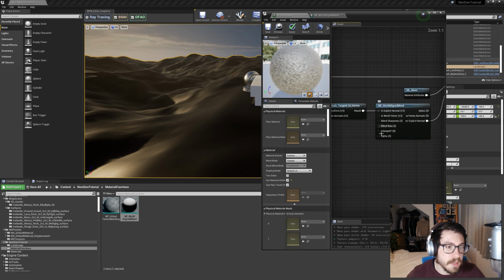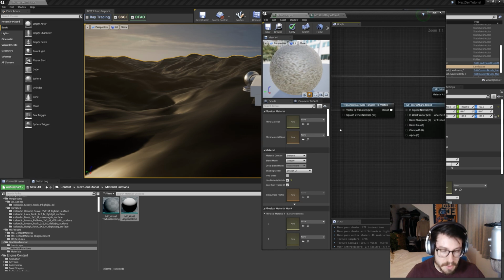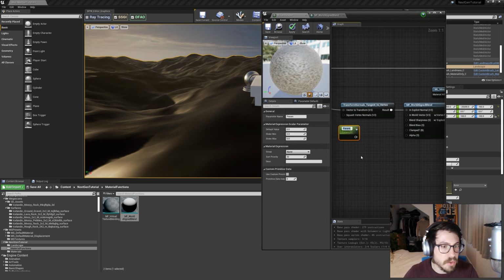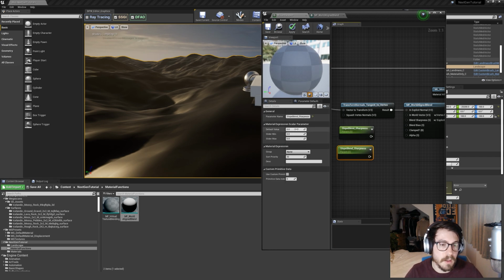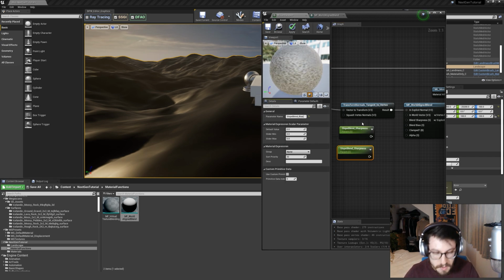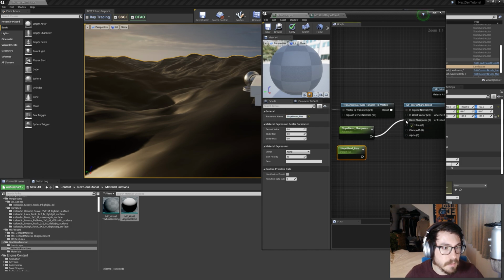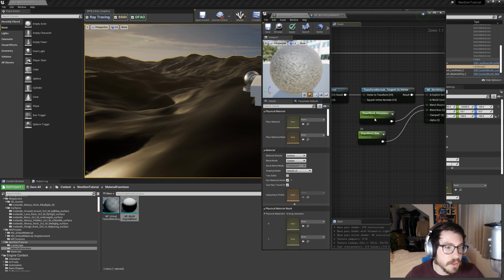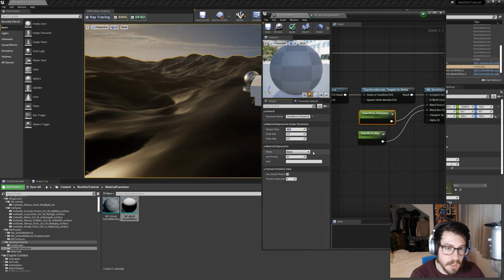We can refine this blend a tiny bit here with two parameters. So let's create those two, slope blend sharpness, and slope blend bias. Good values for these are, I think for the sharpness, something about 30, and let's put that in the right layer blending group as well.